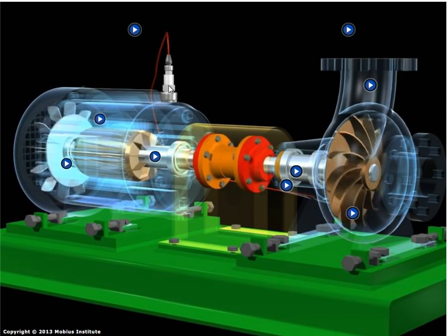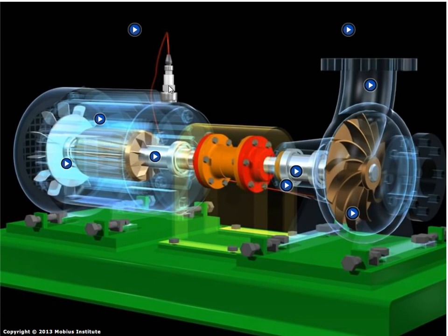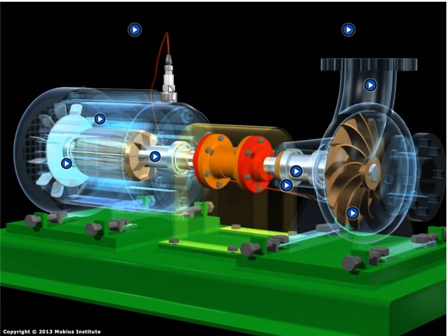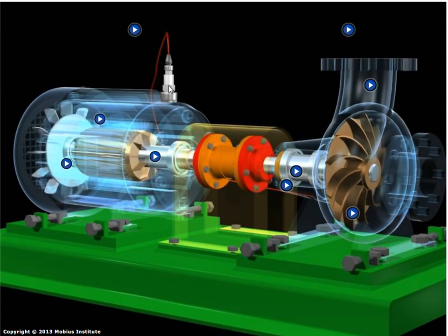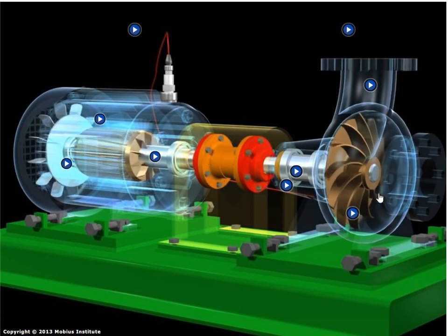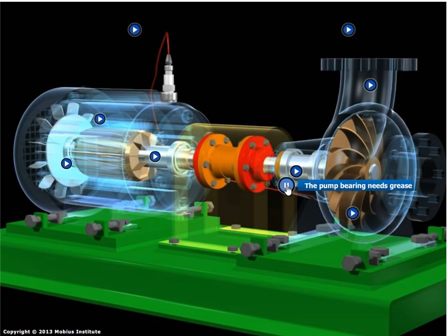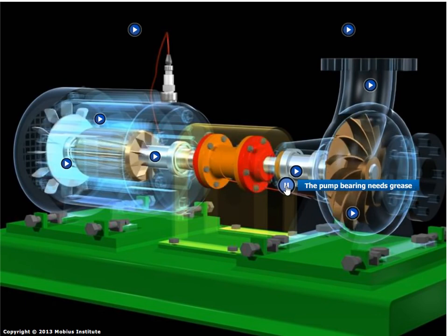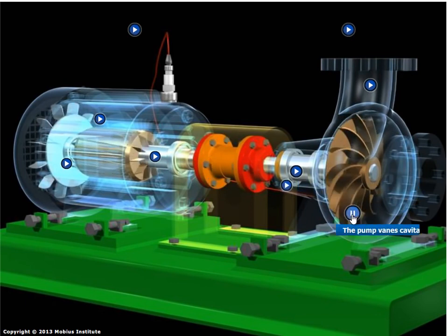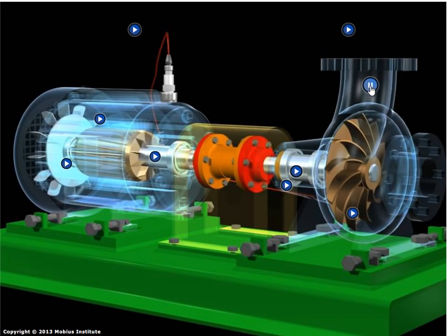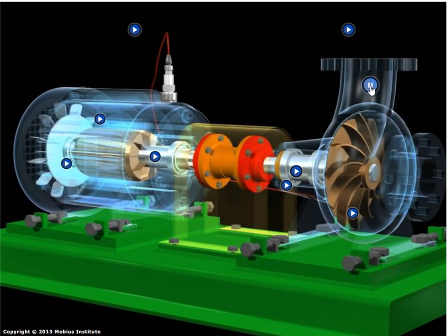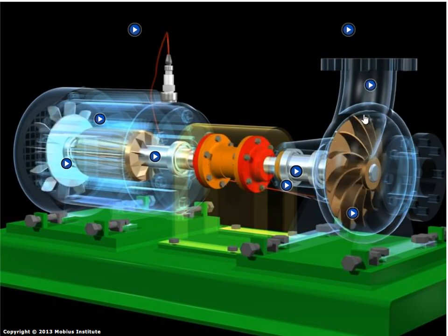They all combine together into one measurement, but separating them in frequency and some of the other things we'll explain let us do that so we get an idea of the health of each of those components. Over this side, that bearing is not in good condition. For the pump, we've got pump cavitation. On the machine head, okay, not many machines sound like that, but anyway.